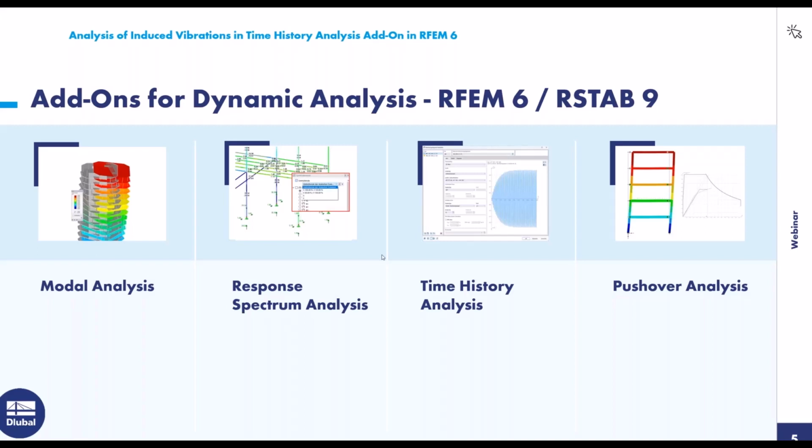Here you can, of course, choose a response spectrum according to a design code, for example, the Eurocode or the US code or some other code, whatever you want to use. You can also create your own response spectra, maybe also out of accelerograms if you want to do this, and then the program will calculate for each FE mesh point internally an equivalent earthquake load, and then you will get at the end, of course, the internal forces for the directions and also the combined reactions of the whole structure.